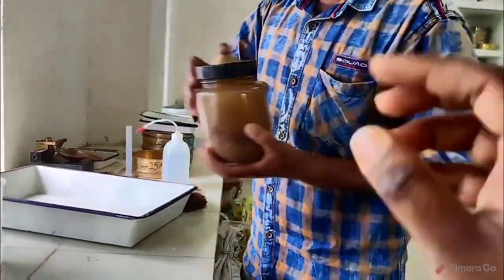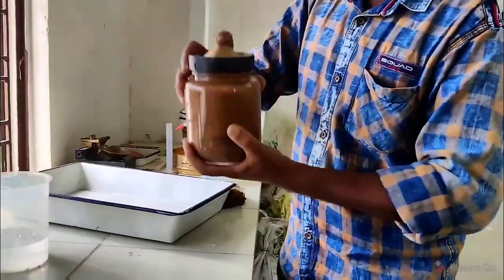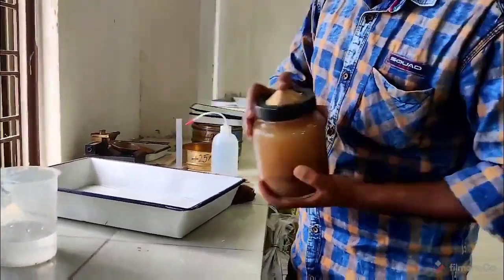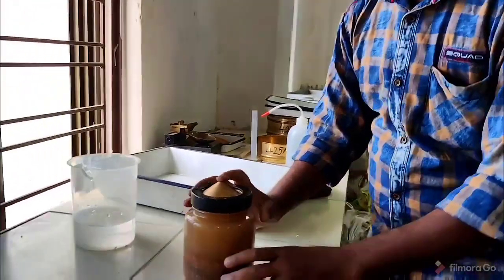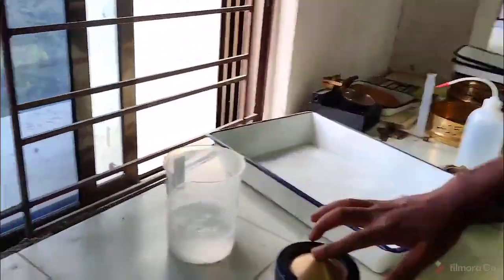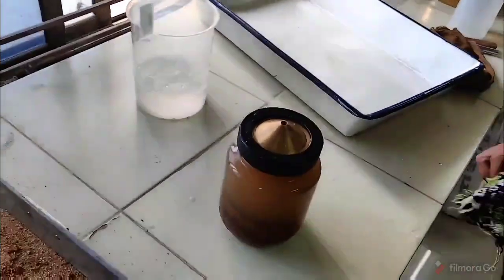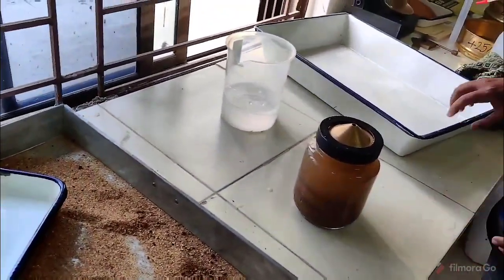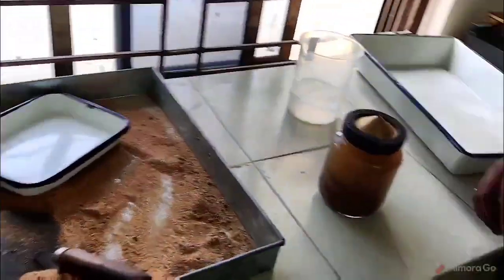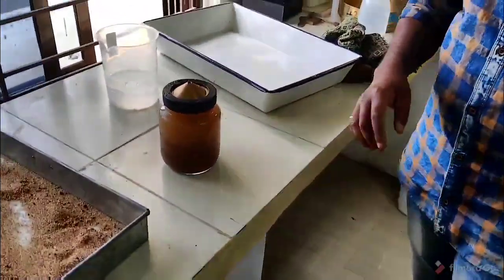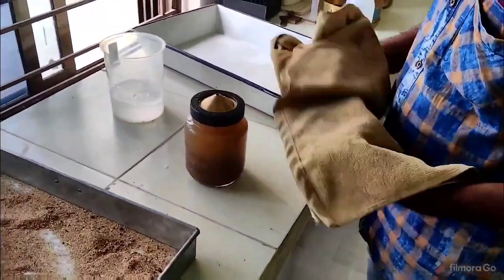During this procedure some water may come out. We'll take care of that. We'll wipe down the water outside of the pycnometer, and again fill it up to the top. Wipe the pycnometer with a dried cloth, closely, carefully.